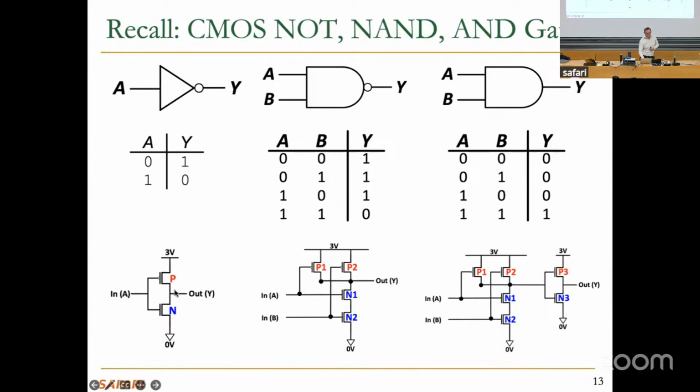to the opposite value. If it's 3 volts, you get 0 volts. If it's 0 volts, you get 3 volts. But for later, we're going to basically say 3 volts corresponds to high voltage, a logical 1, and 0 volts corresponds to a logical 0. This could be encoded in a different way, of course, exactly the opposite way. You need to encode in one way. And if you encode it logically, you basically get an inverter in the logical domain. Makes sense, right?